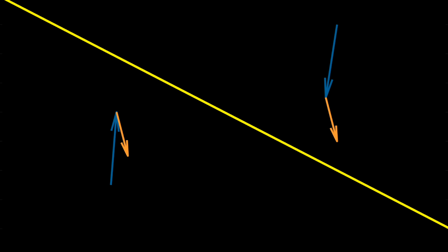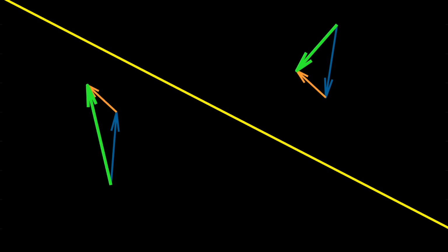That disturbance is going to have some delta contribution to the existing phase plane, which I'm showing here in orange. And the combined effect will be this green arrow. So even with this disturbance, the sliding mode controller still causes the states on either side to tend towards the switching surface. And this is true no matter which direction the disturbance is in.